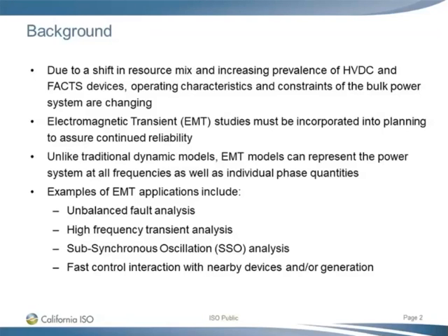So first, why do we require EMT models from the generator owners? Today's grid has changed from 10 years ago, 20 years ago. Now we have more HVDC fast devices, and more importantly, we have a large amount of inverter-based generating resources. Those are all based on inverters with fast control and fast response to any event on the grid.